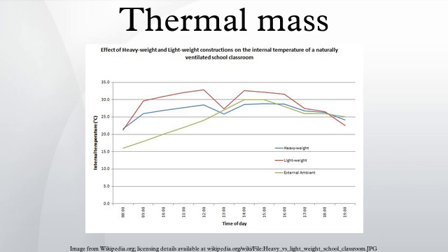For example, when outside temperatures are fluctuating throughout the day, a large thermal mass within the insulated portion of a house can serve to flatten out the daily temperature fluctuations, since the thermal mass will absorb thermal energy when the surroundings are higher in temperature than the mass, and give thermal energy back when the surroundings are cooler, without reaching